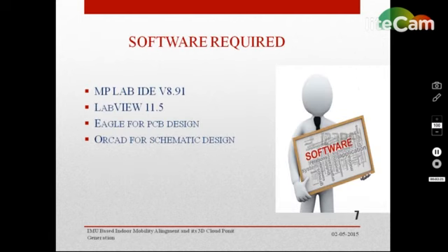The software we have used is MPLAB IDE, LabVIEW, Eagle software, and ORCAD. MPLAB here we use in V8.1, used for PIC microcontroller programming for compiling, debugging, and executing. And LabVIEW here we use in the 11.5 version, and it is used to create a monitoring panel with a serial communication link established between monitoring and the RF receiver unit using serial resource in LabVIEW, and Eagle for PCB design, and ORCAD for schematic design.